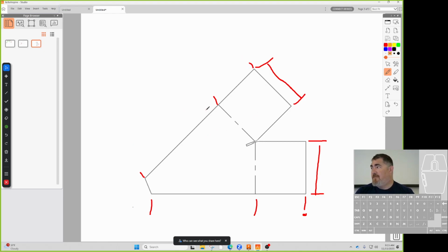Again, the flat pattern is to help us get to the form view, and the form view is where we want to put the dimensions of what we actually want the finished thing to be, right? If you write typical, are you going to write it on each dimension? I would just do a note, both sides the same or something like that. That way they know any dimension here is the same going that way. Yep. So that's probably what I would do on this one. Any questions on that? And I'm not being really picky on the